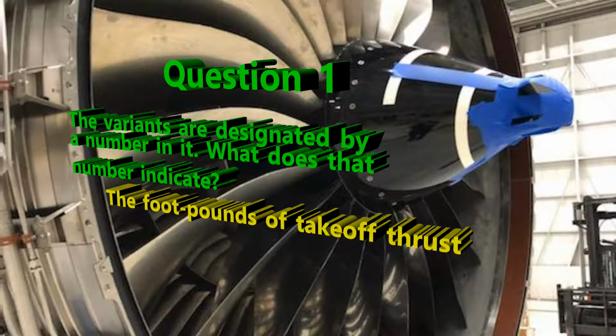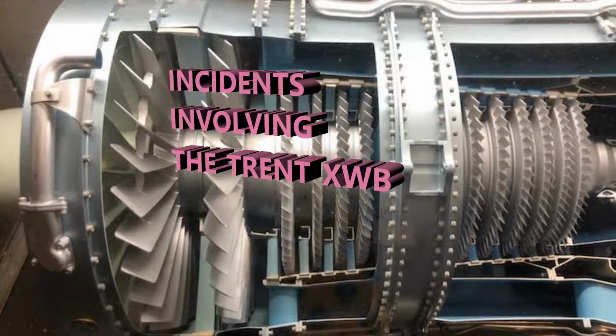Okay, now let's go a little bit into the incidents revolving around the Trent XWB. Certainly we can talk about accidents that occur with aircraft, and in particular I'm talking about the aircraft A350, but how is it relating to the engine itself? There have been incidents having to do with ice that was released from the fuel system that then accumulated on the heat exchangers. What that did is it restricted the fuel flow, because I'm talking about the fuel oil heat exchangers, and then it just didn't have enough fuel going into the engines, which of course causes a problem. So you had incidents related to that.